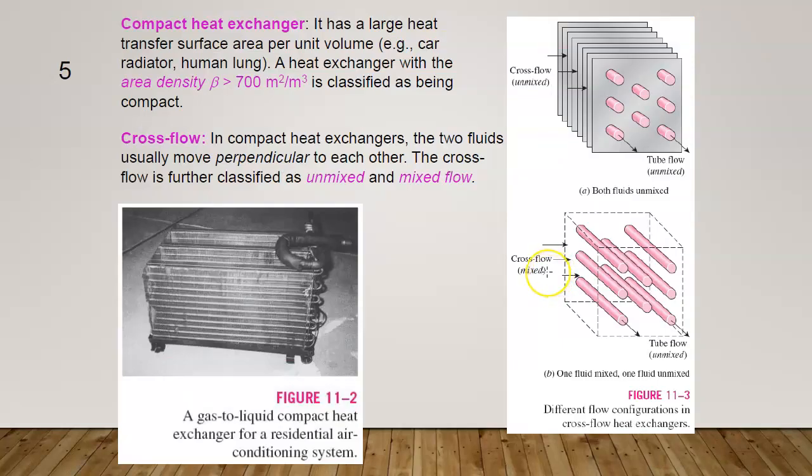Okay, here you could see another type of flow, but not usually discussed. This one is cross flow. Okay, in a compact heat exchanger, two fluids usually move perpendicular to each other. The cross flow is further classified as unmixed and mixed flow.